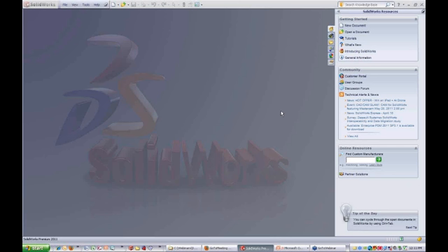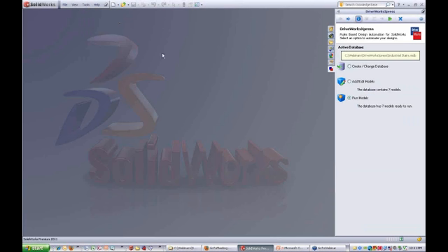Okay. You start DriveWorks Express within SolidWorks from the Tools menu, DriveWorks Express up here. It will now appear on the right-hand side within the task pane. For those of you who may have looked at DriveWorks Express in the past, it used to run in its own separate window in the middle of SolidWorks, but now it's fully integrated into the task pane. This is only from 2011 onwards.